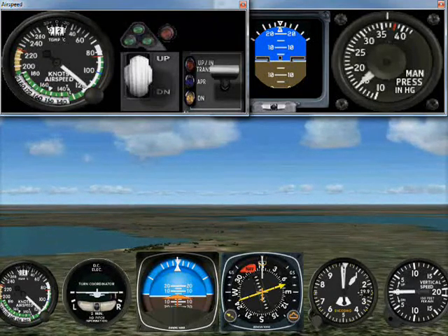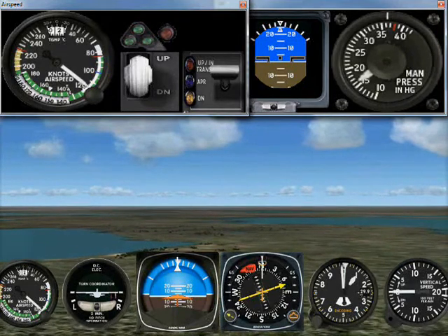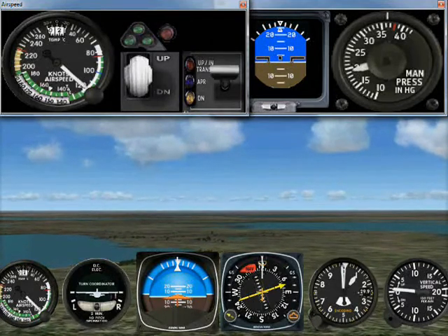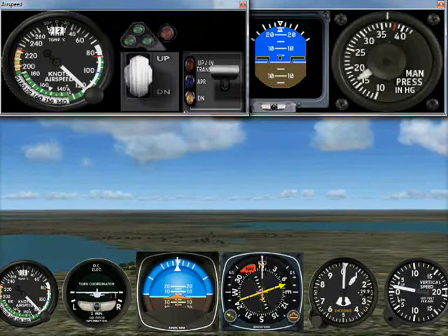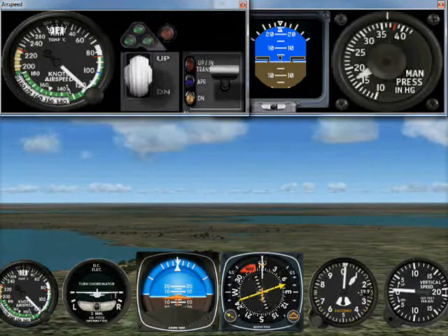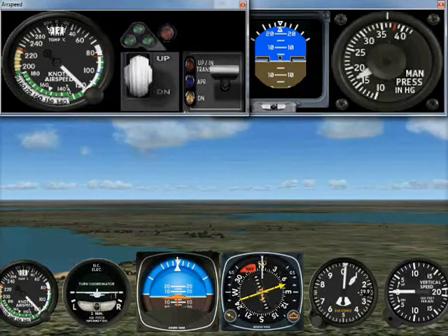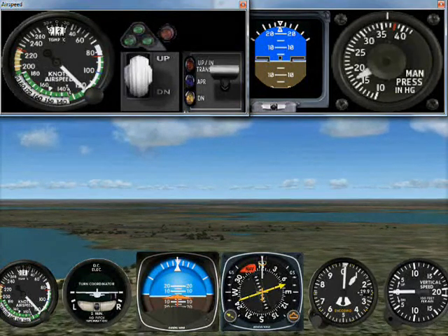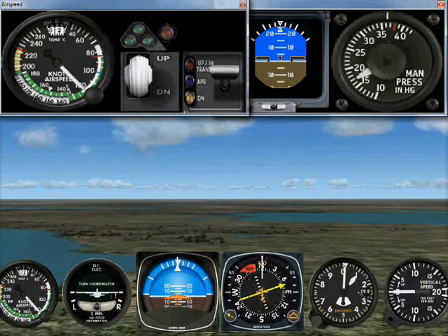In this case, we see that the airspeed drops below 120 knots, so we will select 120 knots as our downwind leg airspeed and must add power in order to determine the manifold pressure that will maintain it. We now see that our downwind leg condition of 120 knots in level flight requires a pitch attitude of +2 degrees and a power setting of 17 inches. A faster downwind leg airspeed could have been selected if desired.